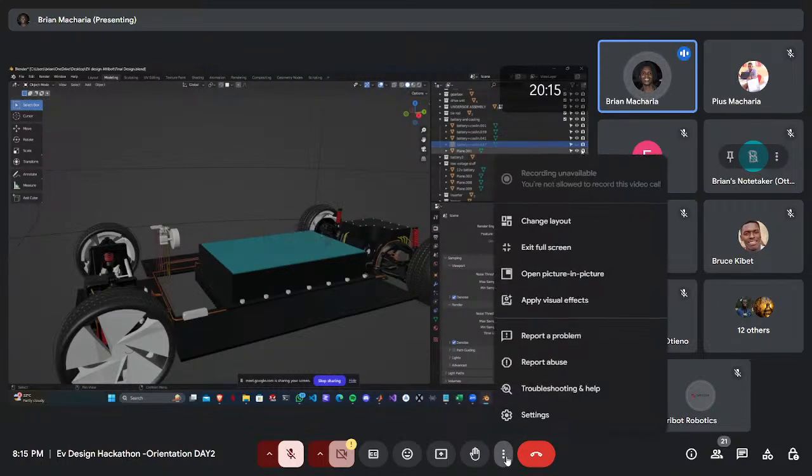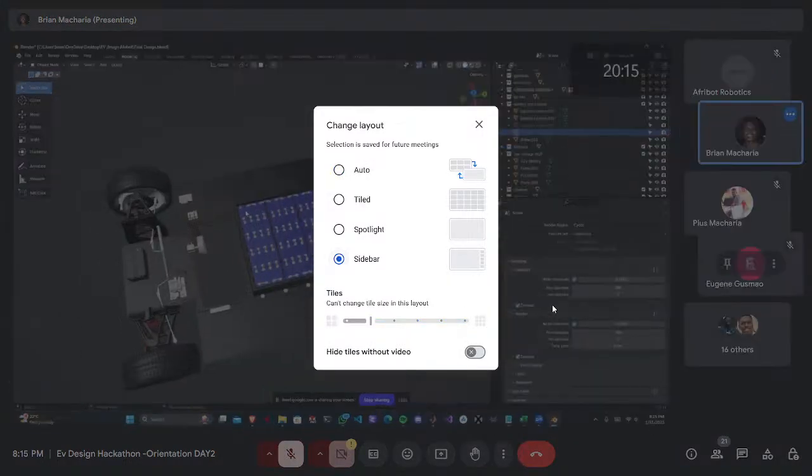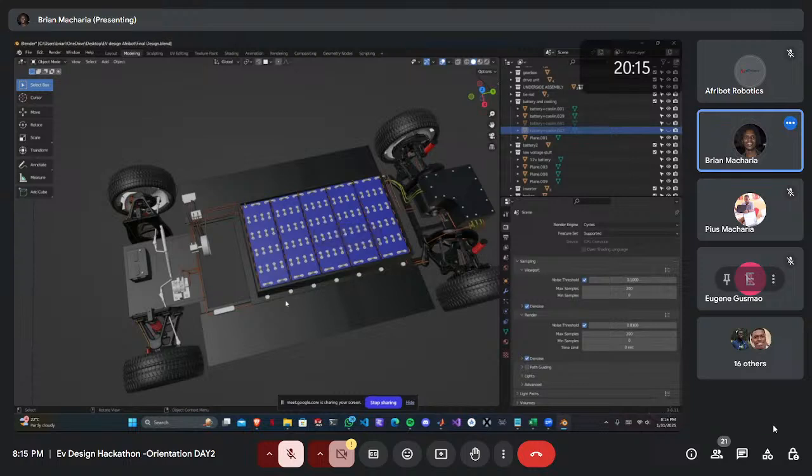And then underneath that are the batteries. There are 100 of them, all connected in series. The battery type I'm using is lithium-ion polymer batteries, and I use them because, first of all, they're cheap, and they have high capacities. You can get one of these batteries at 3.2 volts, but with a capacity of say 150 amp hours in this case.